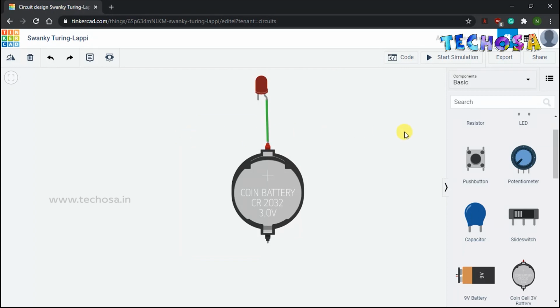Now we can start with a push button switch. It can be placed either in positive connection or in negative connection. All you have to note down is to pass the circuit through this switch. So when the push button switch is pressed, the contact between its two terminals is reached and the circuit is complete. Then the current flows through the switch, which makes our LED turn on.